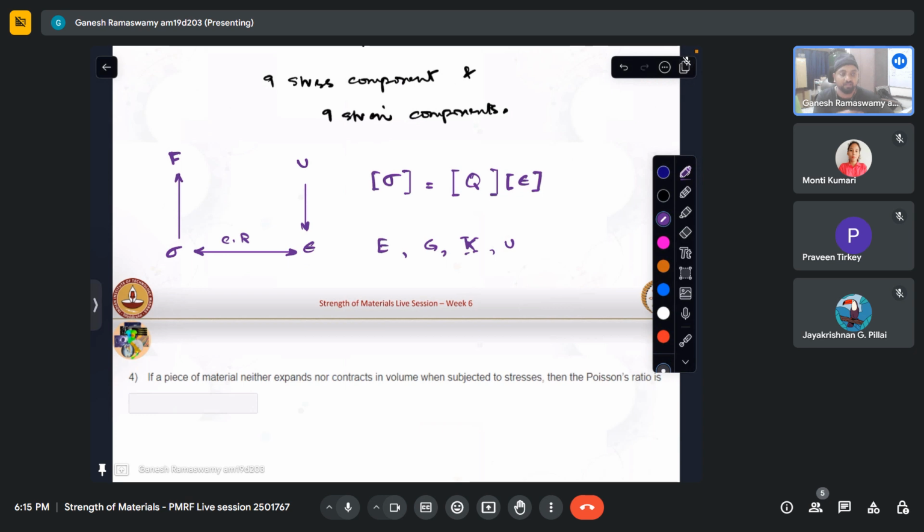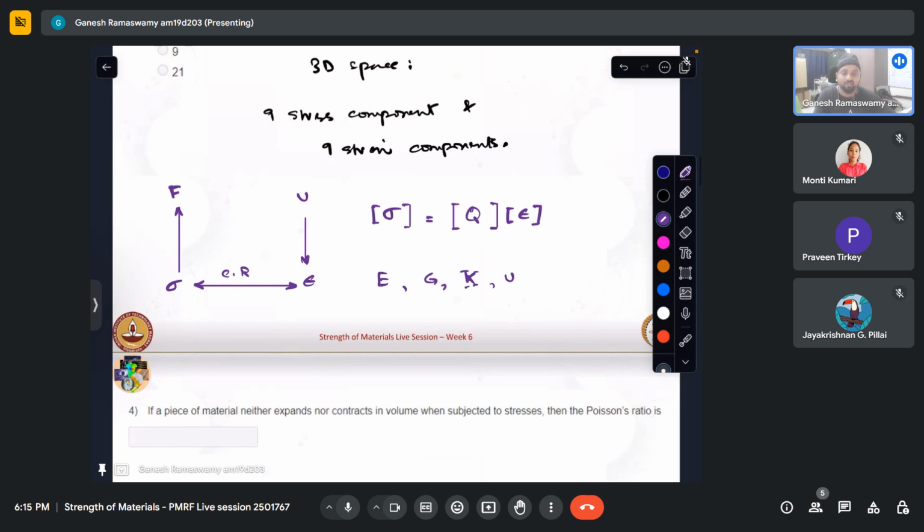And again, there are interrelationships, which are also discussed in the lecture, as to how we can evaluate the rest of the quantities. Once these are known, then this hurdle can be crossed easily from strains to stresses. So once I have some experiment, I know the displacement field, or from some analytical equation, I know the displacement field, I will directly come to stresses. I'll use that constitutive relation for that material. I'll get to strains and integrate to forces, and thereby relate these two in order for me to design the